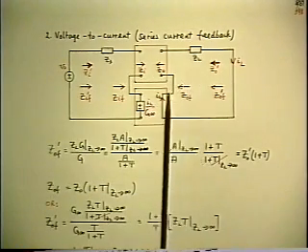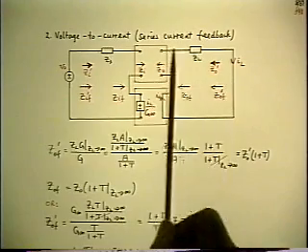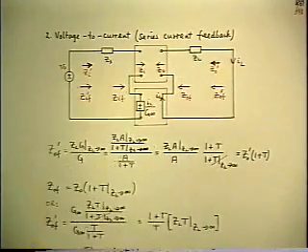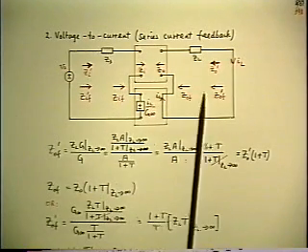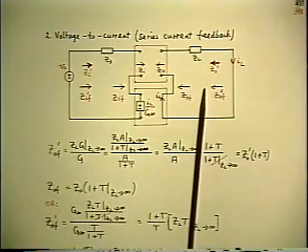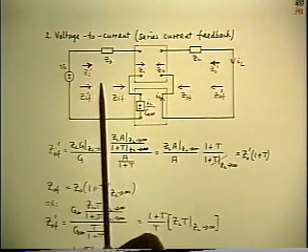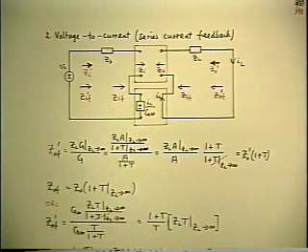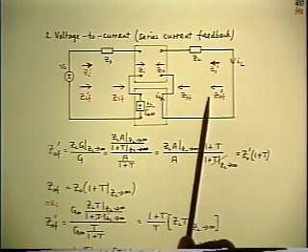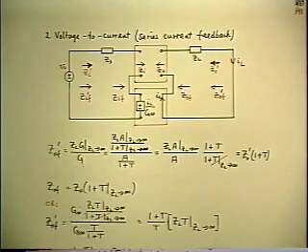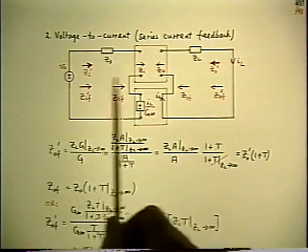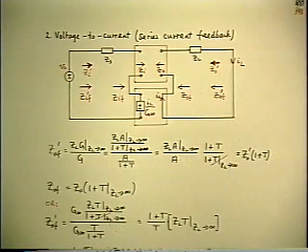Because notice that when we have this current sensing at the output, the configuration of the output circuit is identical to the configuration of the input circuit. So the new formula for the output impedance is exactly the same form as the theorem for input impedance, because the circuit configuration is the same. So all you have to do is take the same formula that we already have for input impedance and substitute the subscript, ZL instead of ZS. Because clearly, since the configuration is the same, the algebra will be the same as well.